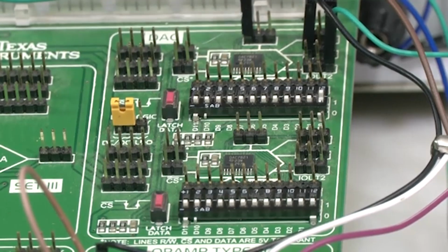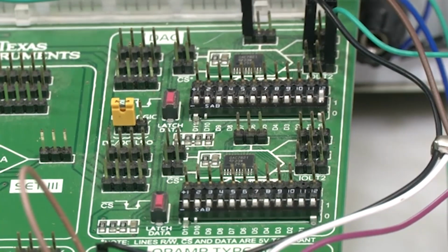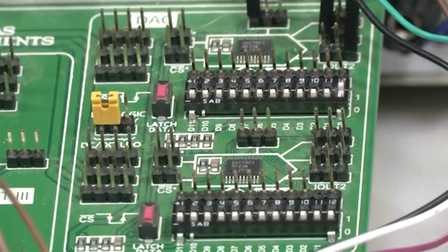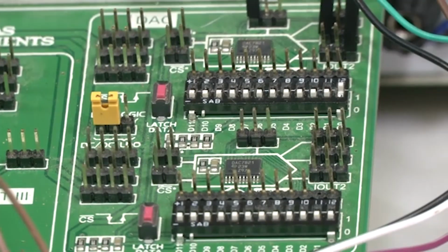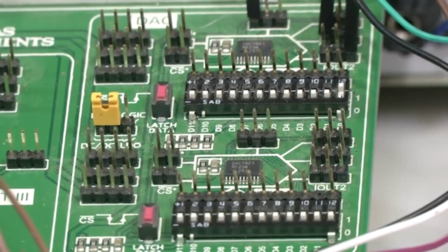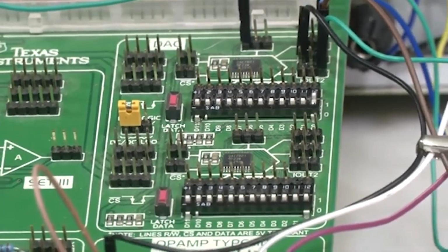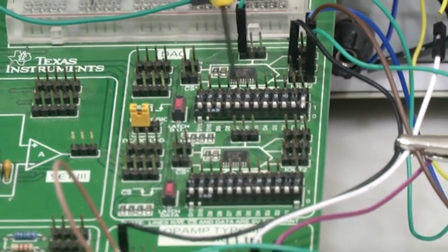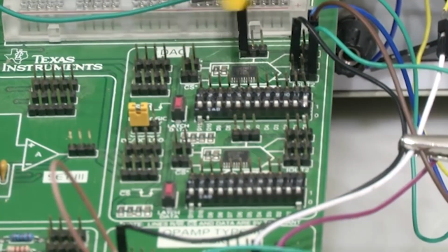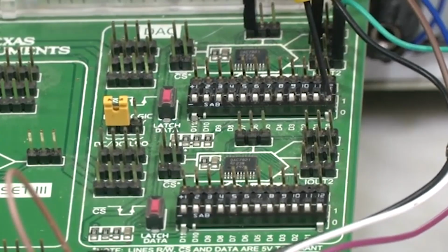Because of the circuit limitations and because we have added a capacitor for gain peak adjustments, we might not get the full output swing, but still we will be able to see the change in output voltage when we change the bit sequence, which is what digital to analog conversion is. The bottom position is 0 and the top position is 1. Now we have given 0 0 0 0 0 0 with the last bit as 1. Let us see what is the output voltage.